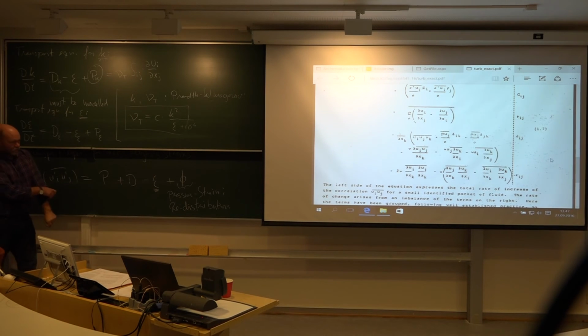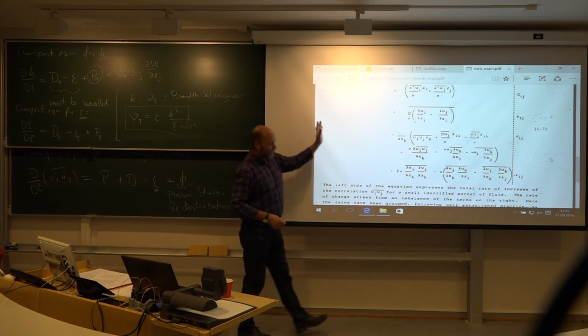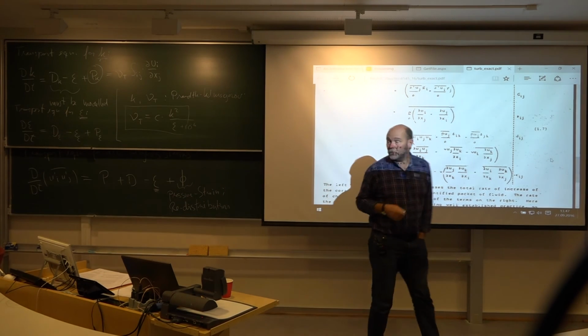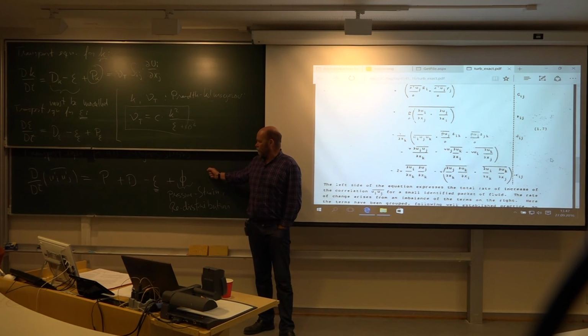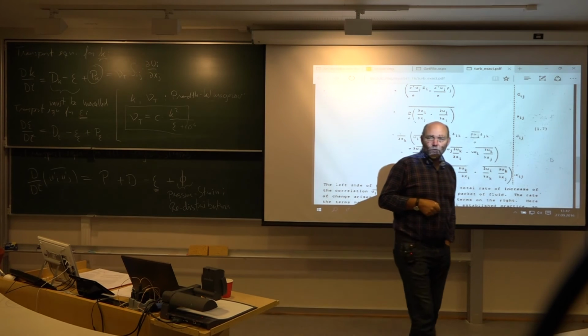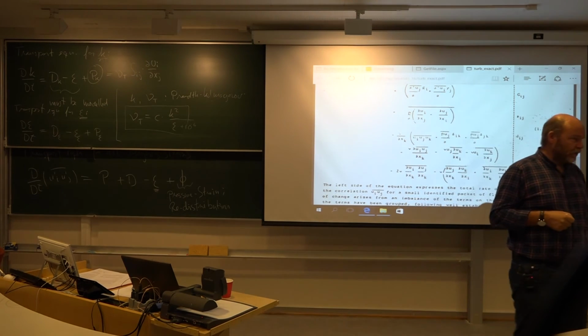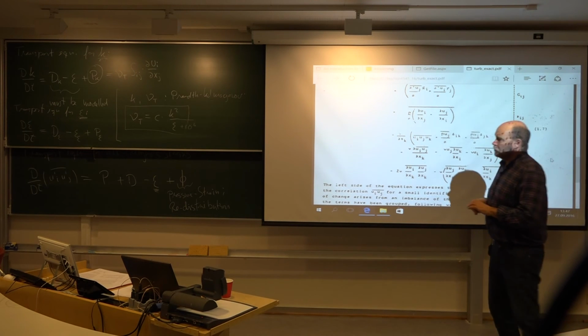And these models are getting quite complex. There's a lot of physics they should cover. So a full Reynolds stress model will typically involve 20 to 25 constants that you have to play around with. You have to find a set of constants suitable for your problem. That can be hard to find.